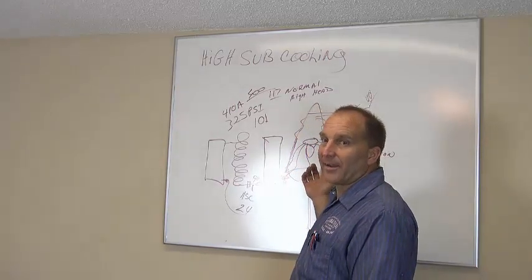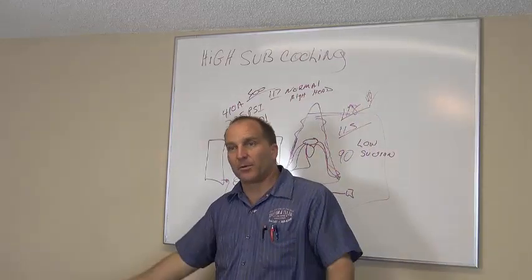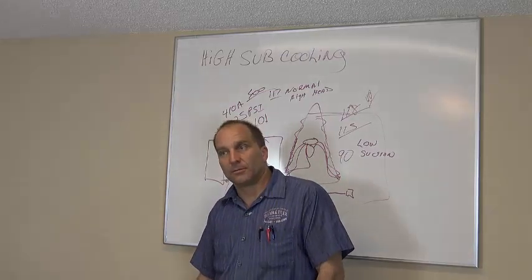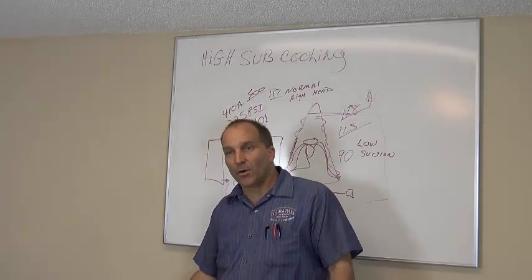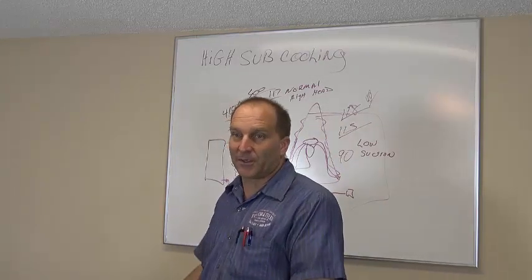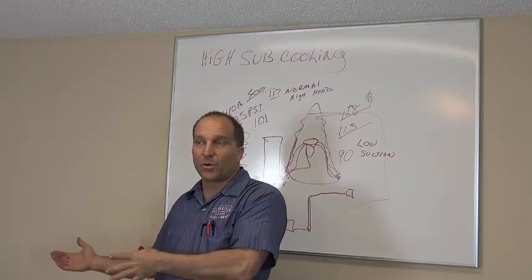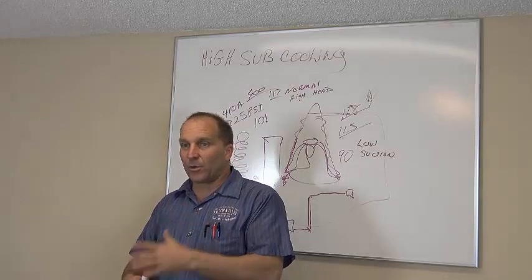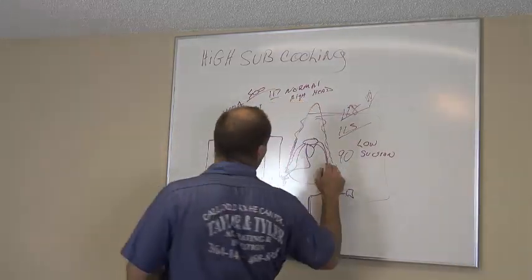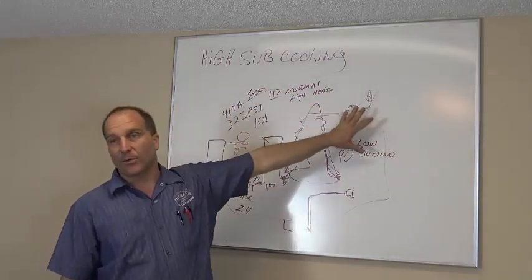Let's just say now you're running a 28-degree superheat and you're running 12-degree subcooling. What's the problem? You have a restriction. Again, a TXV maintains a constant superheat. You know you have a TXV on the system. You know you're supposed to charge this system up to 12-degree subcooling. You do that, you stop, you look at your suction pressure, and instead of reading 118 pounds on your suction pressure, you're reading a 90-pound suction pressure, and you're reading a 28-degree superheat.